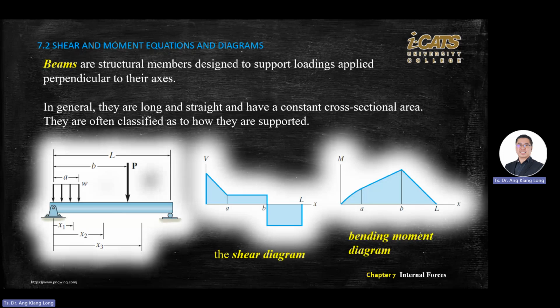Okay, a few characteristics to check your answer. If you have a point that is locked and there's a force pressing on it, usually you have a shear force in that location. You have a positive shear load in that position. Same with this one. It's only either positive or negative, depending on your analysis. And then the moment, you see it like a slope of a hill, right?